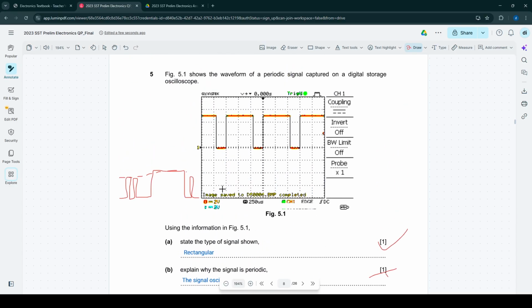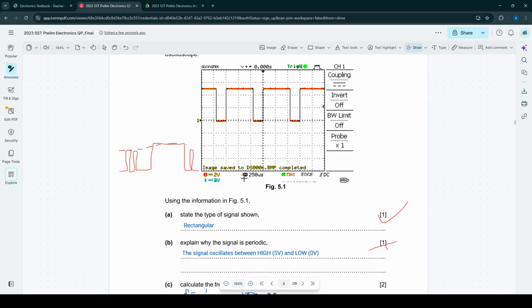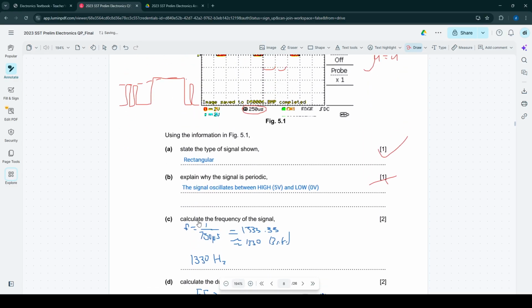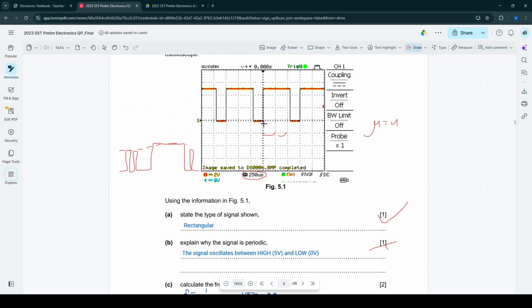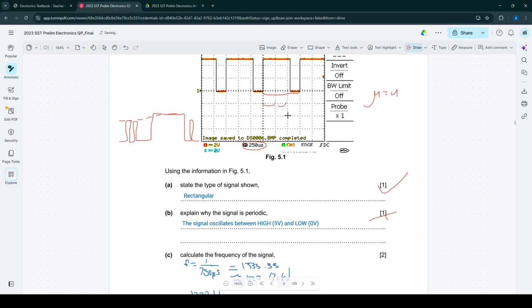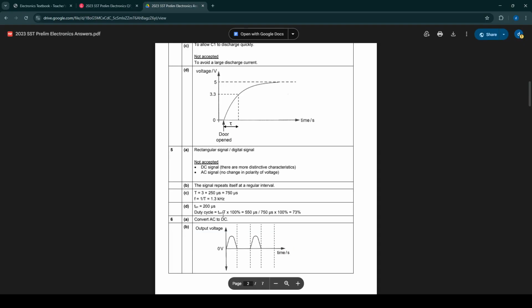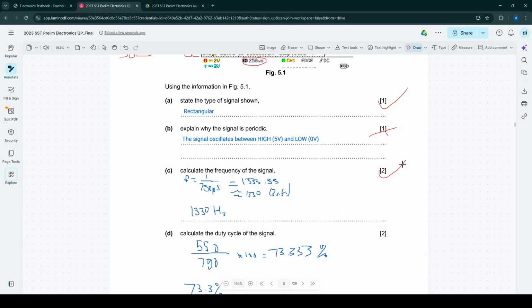Okay, anyway, frequency. This is in microseconds. So each interval here is 250 microseconds. U is micro; some notation will have it like this. So frequency is 1 over the period, and each period is around here because it repeats. So it will be 3 of 250 microseconds. If you calculated it right, you do get it. So yeah, this is correct.